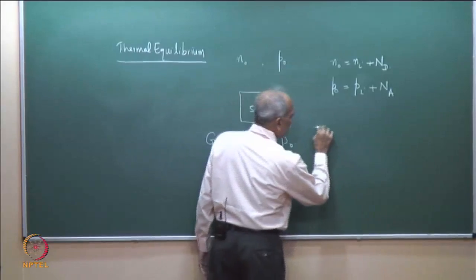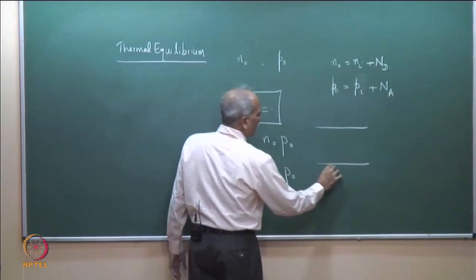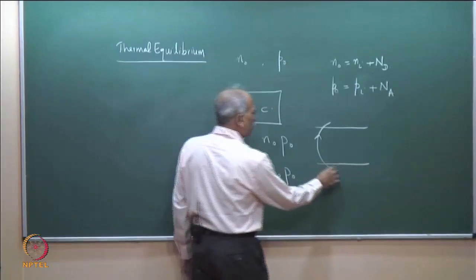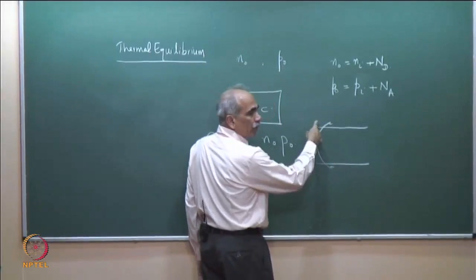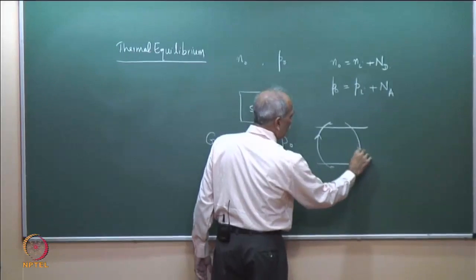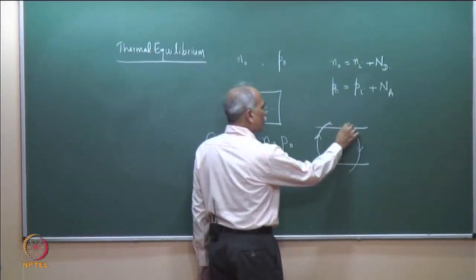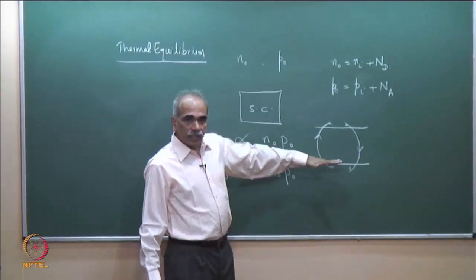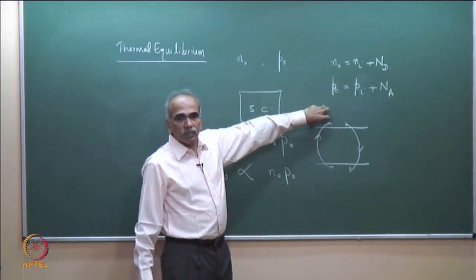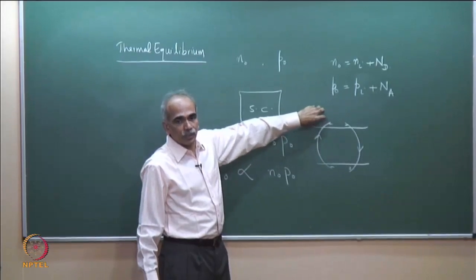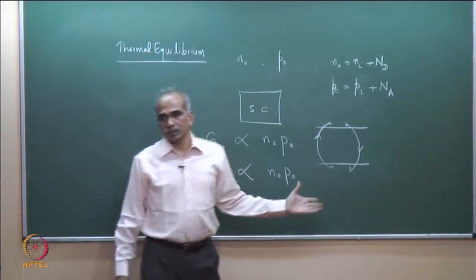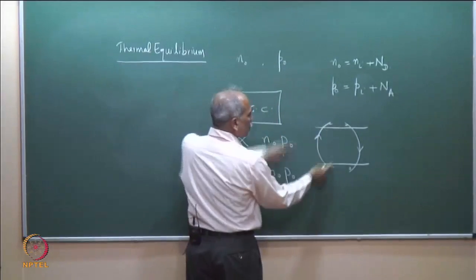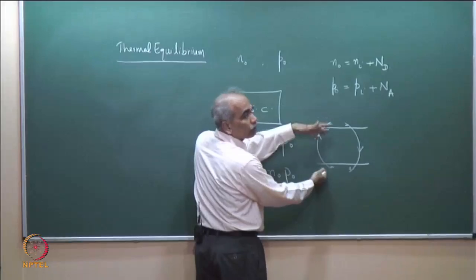In a semiconductor, as we discussed earlier, carriers are continuously generated because of thermal energy. Carriers continuously make upward transitions, but they also make downward transitions, which means electrons keep recombining with holes. At steady state, N0 is the concentration of carriers and P0 is the concentration of holes.